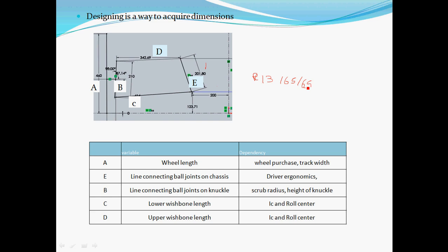So by using this, I can calculate the height of the wheel at the maximum inflated position. Okay, and we'll go with that. Because you design for endurance, and before endurance they give you an option of optimizing your air pressure inside the tire. So maximum inflated position is good enough for you. So that is how you will get your dimension A.